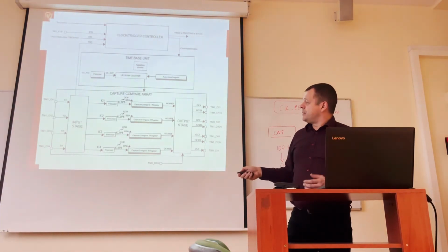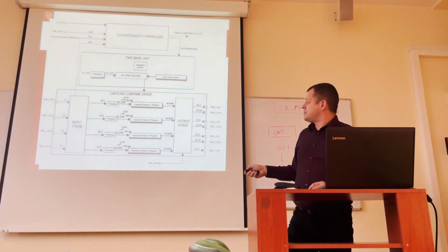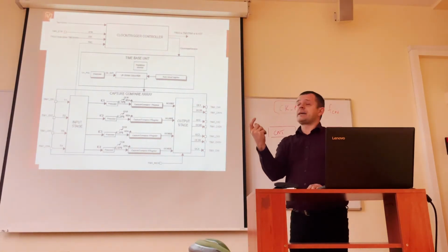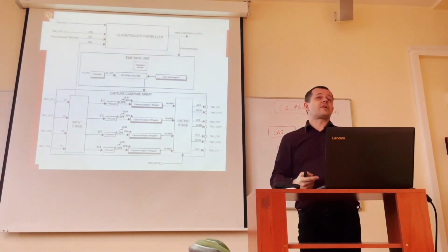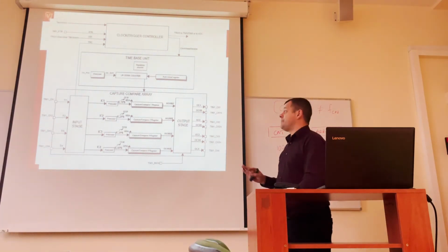So if a pulse happens here, we get a snapshot of the up-down counter, and then in the interrupt we can analyze how much time it took between two occurrences of the event. That's the major functionality.